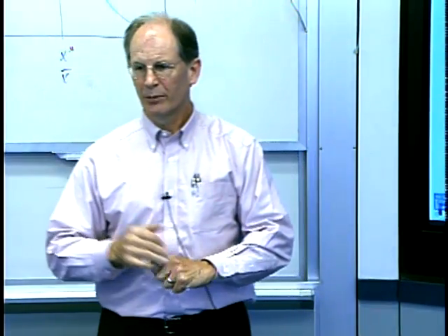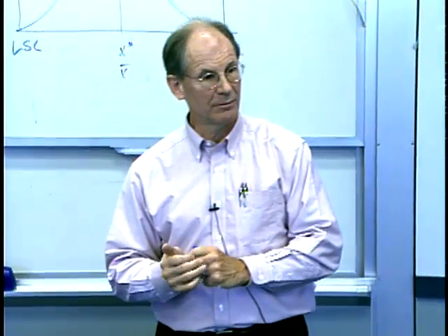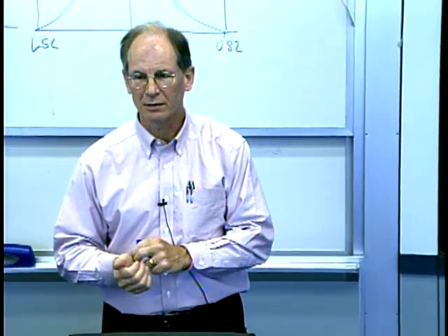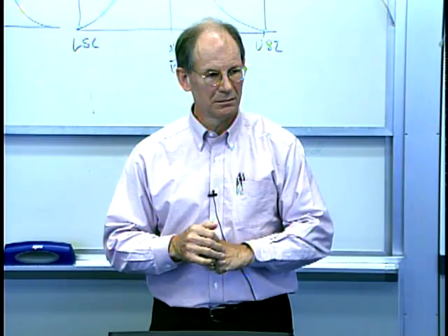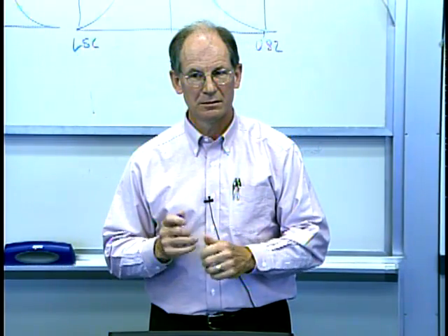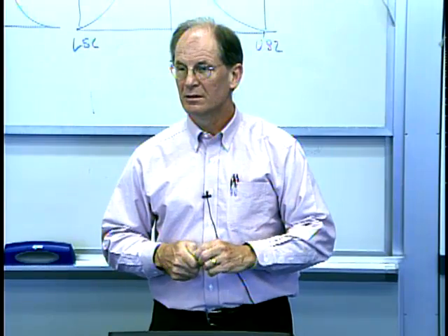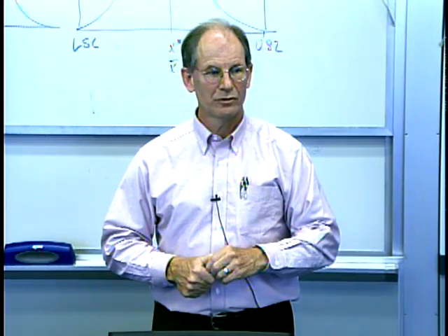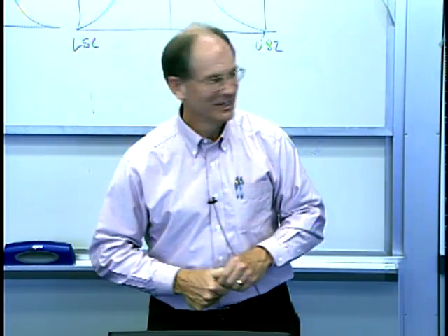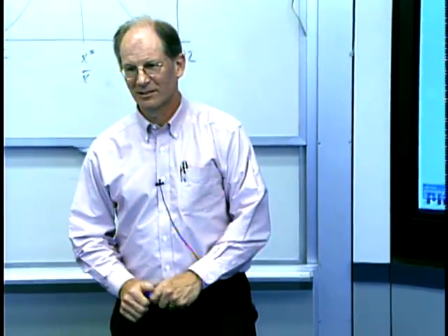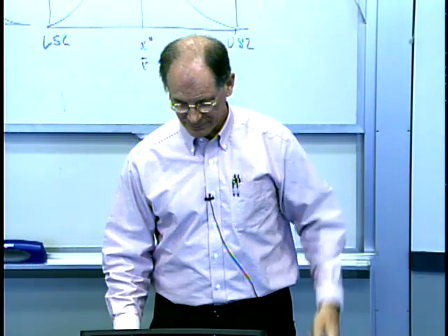Okay, if that's the case, what's my parts per million, which many companies will use to measure their quality? What's my parts per million bad parts? Three out of 1,000. So it's a lot. So yeah, CP of 1's not particularly that good, okay? Companies like to have it a lot higher than that.